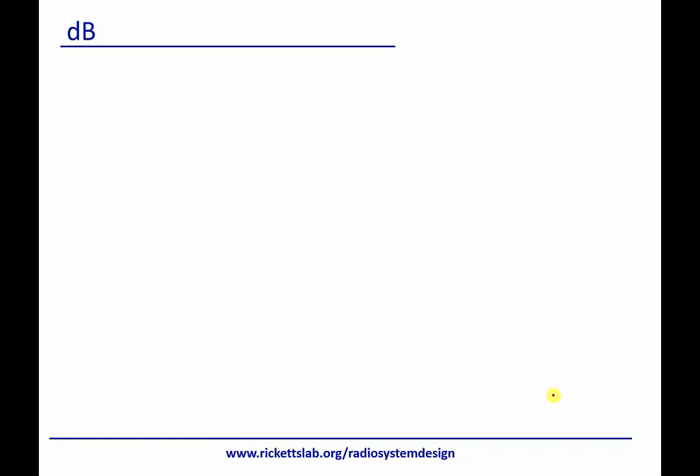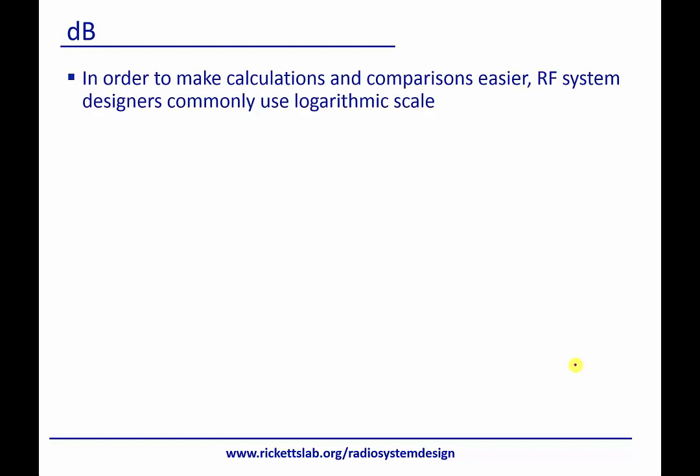dB is something that you've probably encountered before. dB is very useful to make comparisons for multiplication. We use the log scale often because we can have signals that are as low as a picowatt or as high as a kilowatt in wireless systems. That's 10 to the 15th, so 15 orders of magnitude change in signal strength. With that kind of change, using a logarithmic scale can be very helpful.